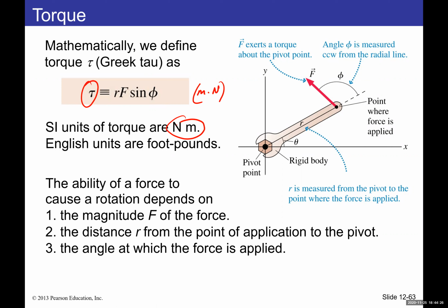And then what we have here is the rotational direction, counterclockwise and clockwise, which can also be used to give us direction for the torque, because torque is a vector. That means it has a direction. So whenever the torque gives us a rotation that is counterclockwise, then it is positive. Whenever the torque gives us a rotation that is clockwise, then it's negative.